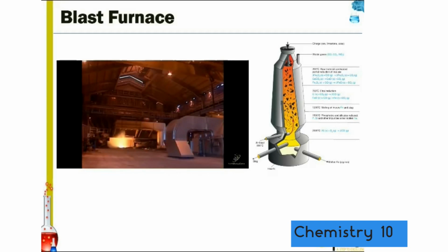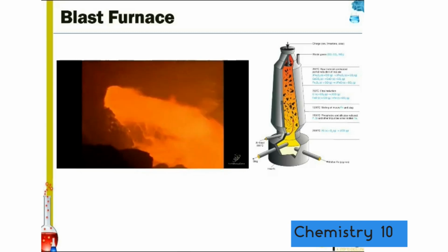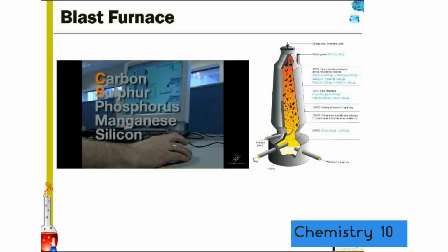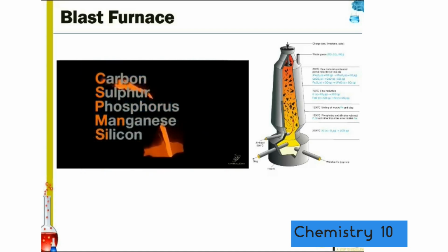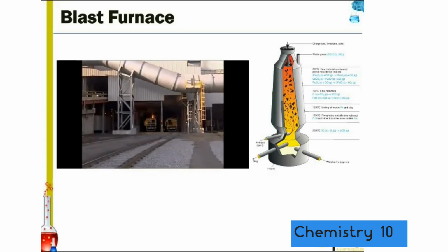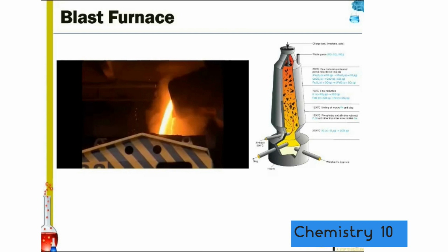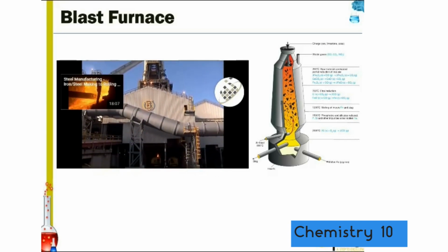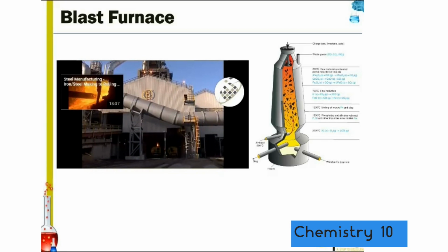The molten iron we get from a blast furnace, or hot metal as it's known in the industry, isn't pure iron and contains the elements carbon, sulfur, phosphorus, manganese and silicon. To make steel, these elements must be removed or reduced and other elements added, depending on the type of steel being made. The carbon content, at about 4%, makes iron very brittle and unsuitable for rolling or forging. And although iron can be used for castings, most of the iron produced is for processing into steel.